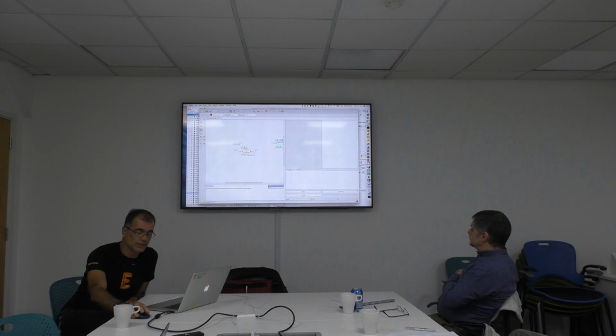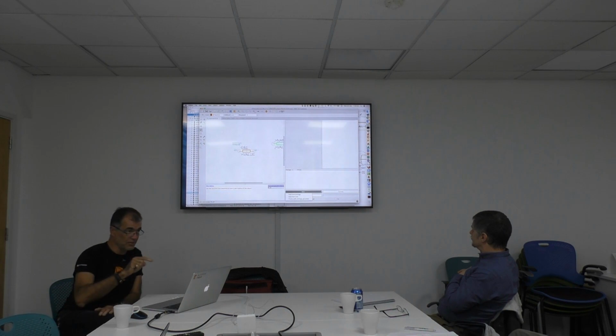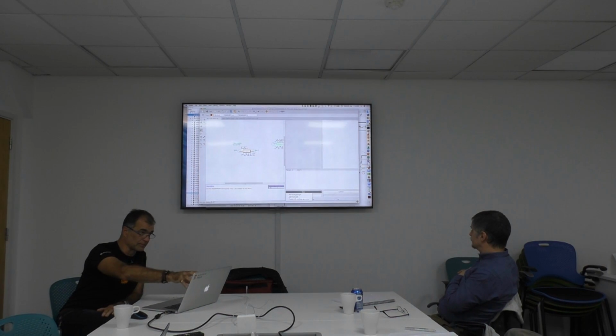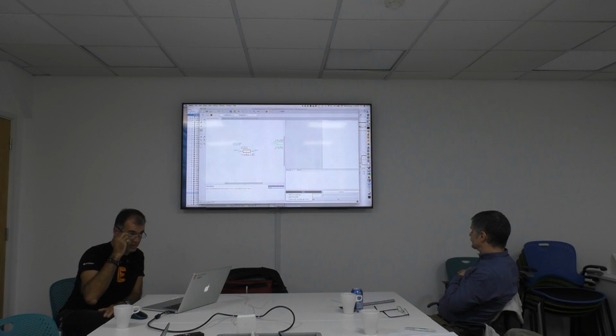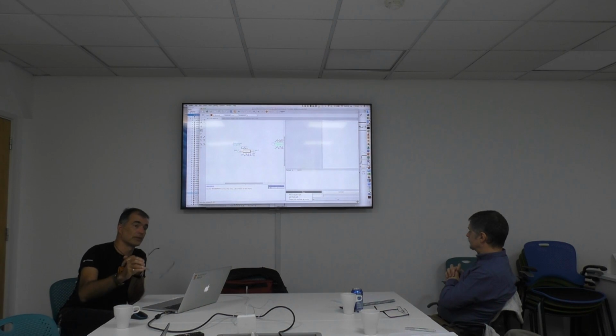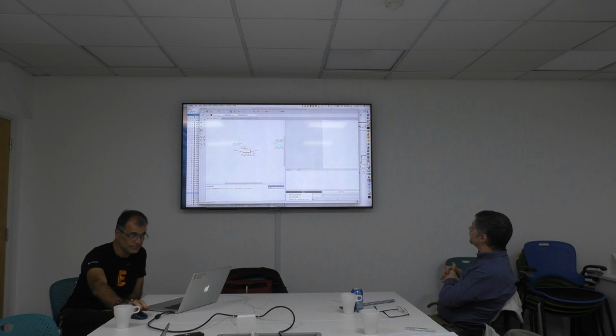Next step, I of course need a package. The right hand side is more for the packages, and there I can click on New. I could also decide now to add a local package, or add from it. That's the same as we had in the beginning. So with the new versions, you could also start here and say, I create a device. I already have a symbol, but I could now start creating the packages. That's also possible to do here directly in the device.